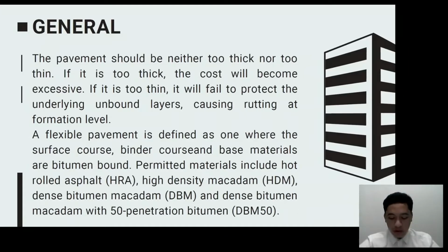In order to maintain workability, the stones are usually less than 1.5 inches in size and often less than 1 inch.